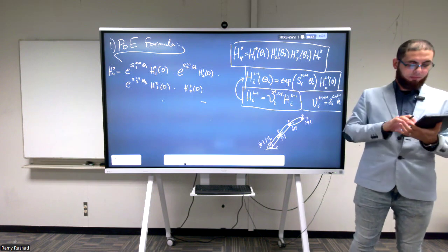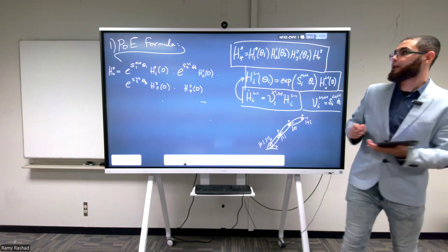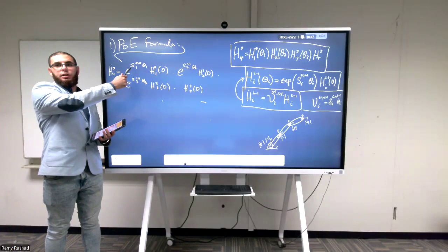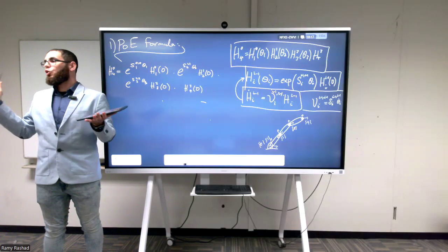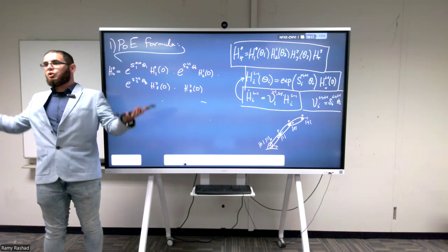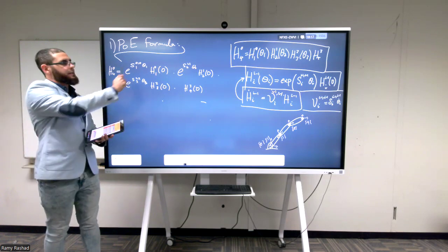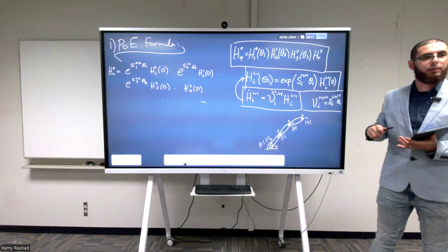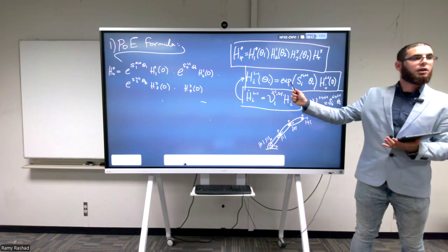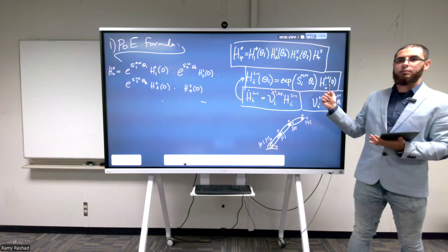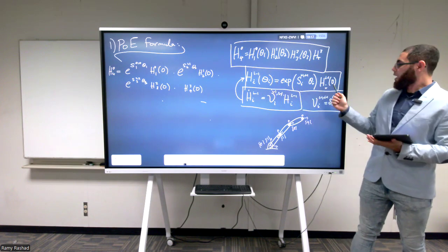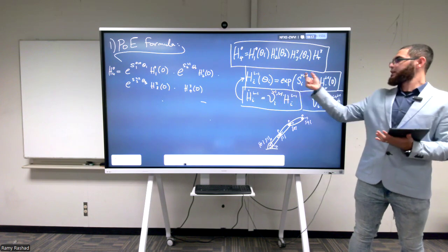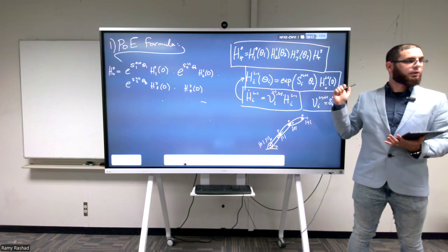There's a nice property, and the property is the following: when we have the matrix exponential multiplied before and after by homogeneous transformations, we can take these homogeneous transformations and put them in the exponential. This is just a sketch of it, but if you look at it in detail, it will make sense. If I take this matrix exponential and multiply it from the left by H i minus 1 i, which is the inverse of that one, both of these would go inside of the exponential. So this is a matrix property.